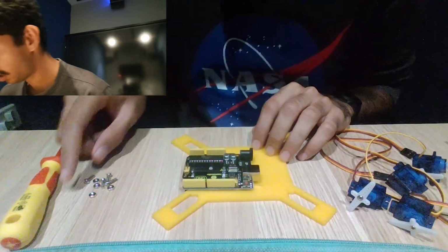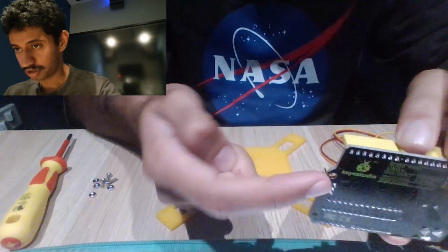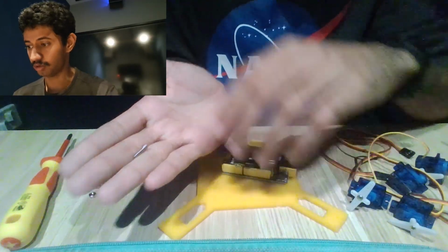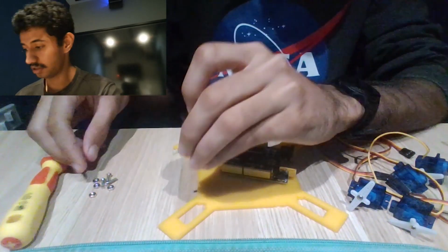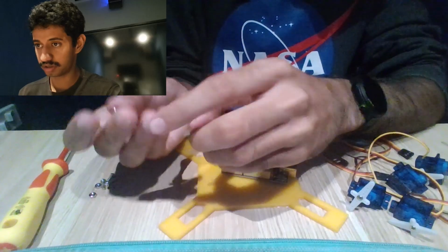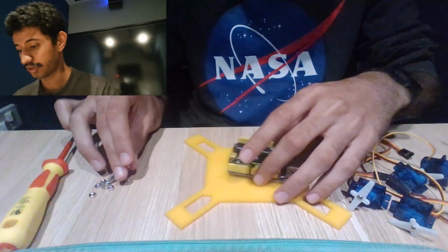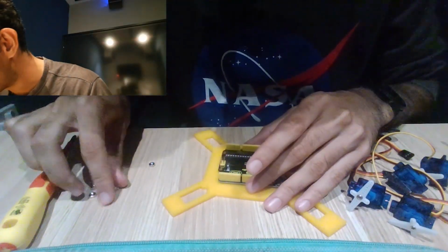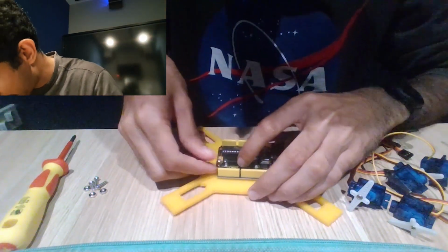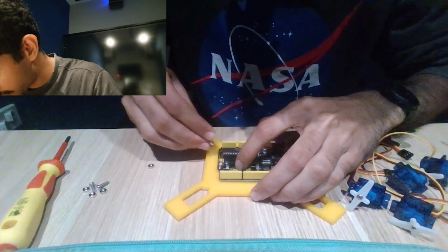Now, a few things. These correspond to this. This is a 3.2 millimeter diameter hole, and these are M3 nuts and bolts, which means this is 3 millimeters. So that's fine, because since this is about half a centimeter more in diameter on the outside, it should be able to case this. So the idea is now to quickly just place these here.